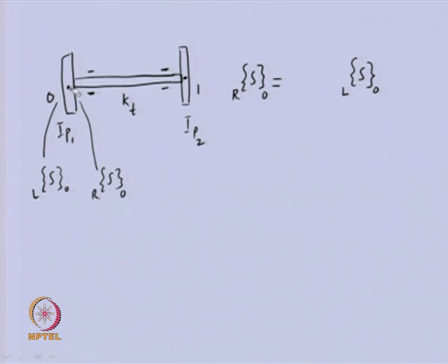In between there is a disc, so we need to multiply this state vector with the point matrix. We know the form of the point matrix, which we already obtained earlier.